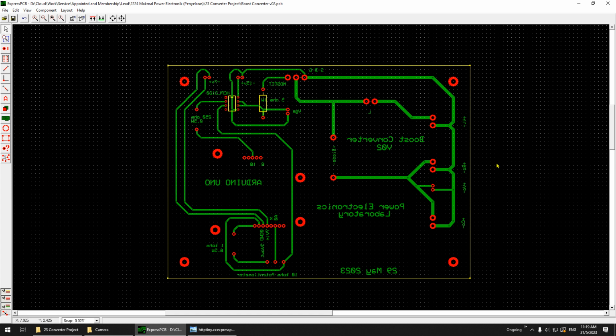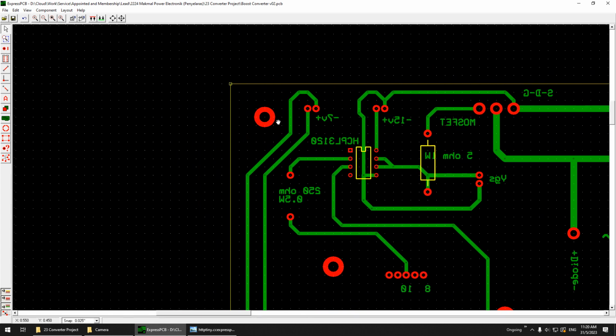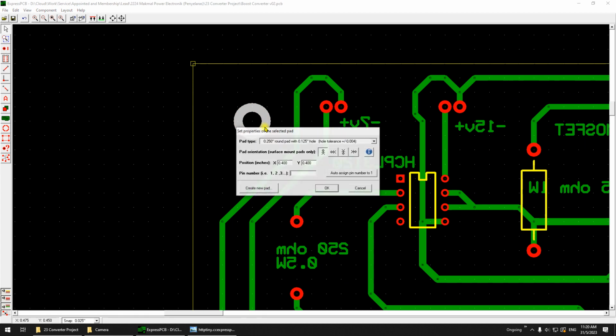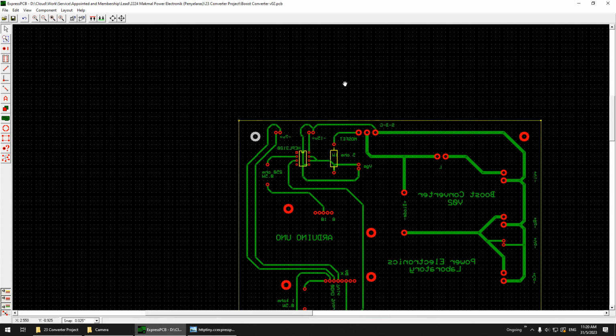In your design make sure you put a PCB stand, because if you put the board at the desk directly, sometimes on the desk you have some sort of metal dust, and it can short circuit the system and damage most of the components if this occurs. So that's why, like it or not, you have to buy a PCB stand. It's only around 40 cents for one. So that's why you have to prepare the PCB stand. For this one, I suggest you choose a 0.25 pad with a 0.125 hole. So that is the first thing that you have to do.